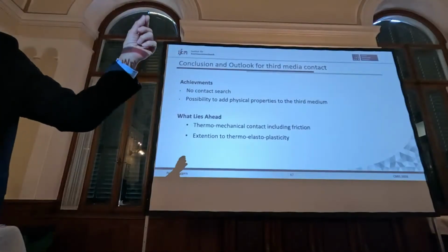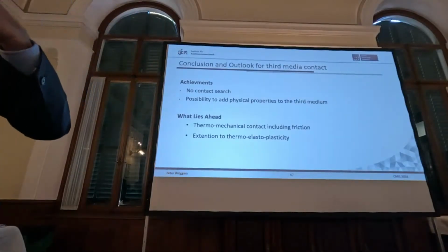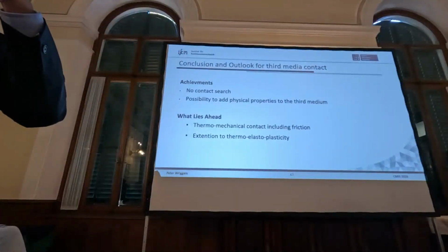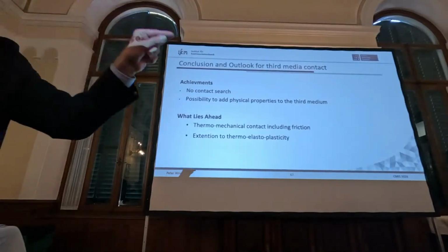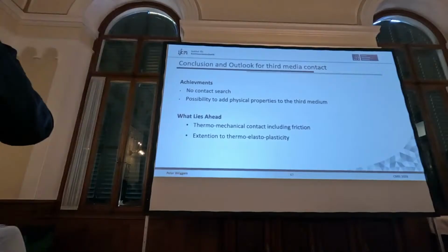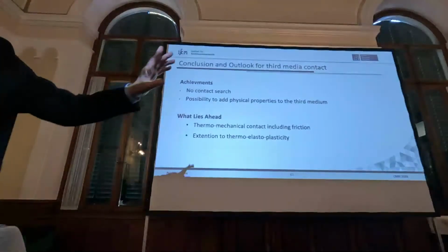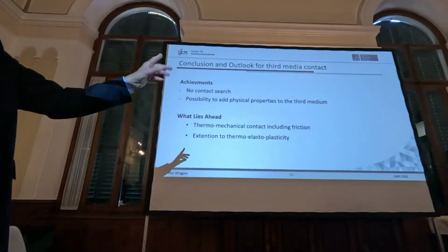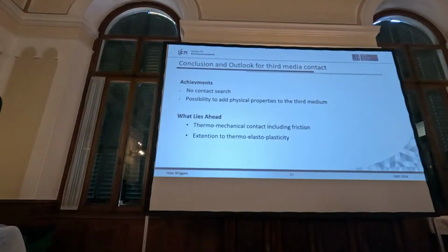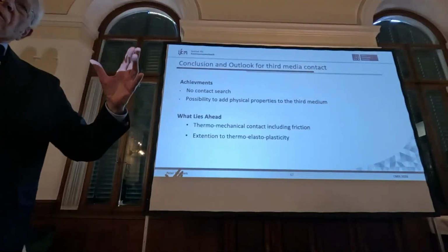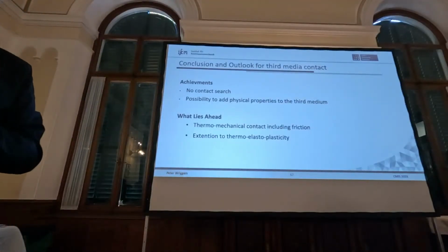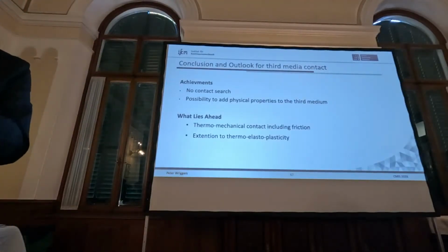But think about it, when you began, you had a mesh. And this mesh actually is sitting, the nodes are still connected. So you have to be able to cope with this sliding, which is done by the regularization, but only, let me say, for smaller portions, not for large sliding. So I think that's also the problem. If you have large friction, then eventually it doesn't work. But for small friction, and if you have small movements, I think it will work.